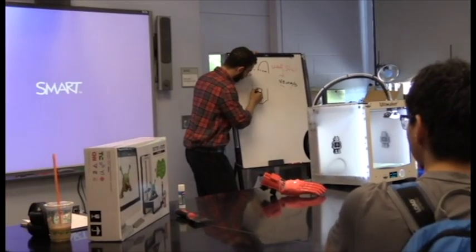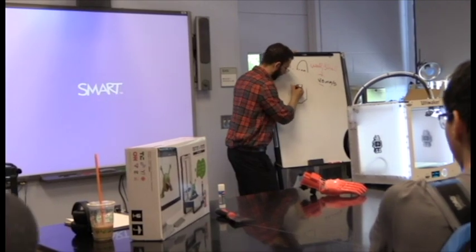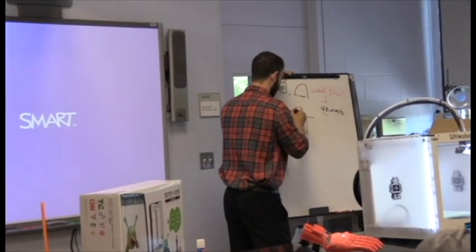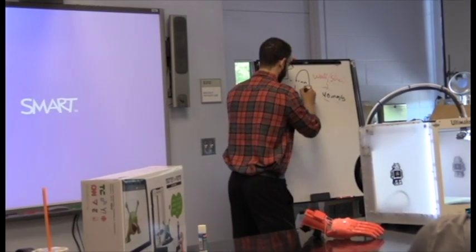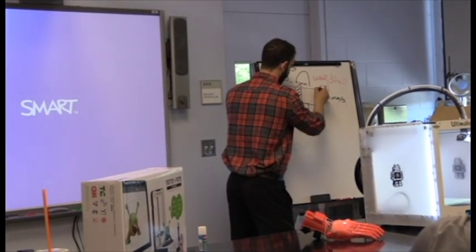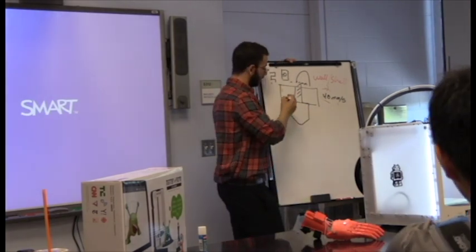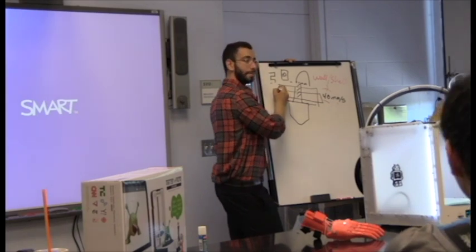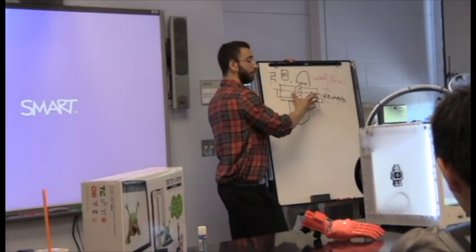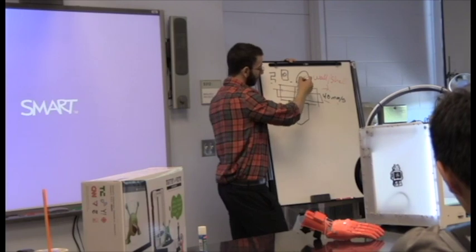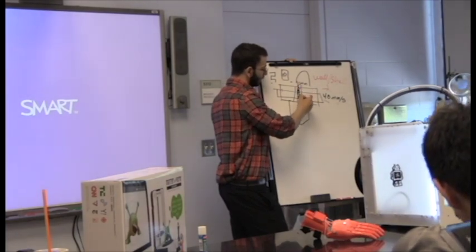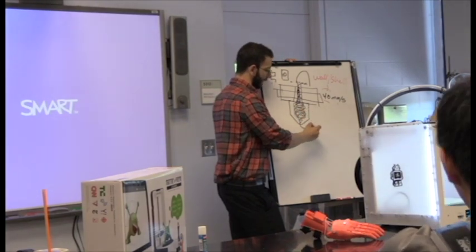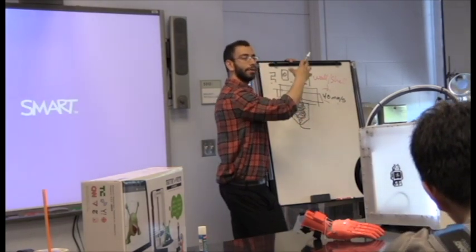But it has a little extra gap from where it actually heats up. It has a heating element. It's like a little block that this threads into. This threads on the inside, and there's an aluminum block in here. And there's a little rod that heats up this whole aluminum piece, which heats up the nozzle. As the filament goes through here, it already starts melting, and it builds up inside here, and then it kind of spools out as you walk it through, because it's kind of gravity fed.